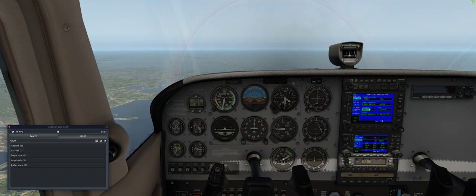So if I wanted to descend at 800 feet per minute, I need to start my descent in 10 minutes 42 seconds. If I don't want such a steep descent, and I just want to descend at 500 feet per minute, then I start my descent in 9 minutes 22 seconds. And what does this mean? This means right now, if I was to start my descent right now, what descent rate would I need to hit 2,000 at WUDAB? And the answer is negative 121 feet per minute. Now it's 122.